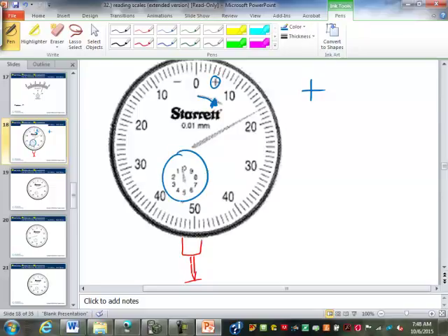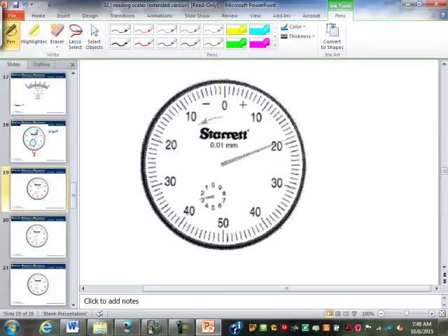Then we got to look down here at this little indicator. Now this one is in millimeters, so this is saying whole millimeters, 0 whole millimeters, so 0.0. And this is 17, you got it. This one here, it's in the negative direction, so it's negative 1, 2, so 2 whole millimeters. Is this 0.19? 8.1, very good. We're reading in this direction, so 10, 20, 30, 40, 50, 60, 70, 81, 2.81 millimeters.